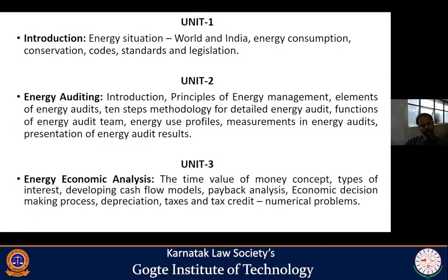Not only the transformer; at different parts of the industry we can see different motors or electrical machines being used. Again, we are going to measure the energy consumption of each and every piece of electrical equipment, and try to give a solution, because some of the motors will not be running at higher efficiencies.